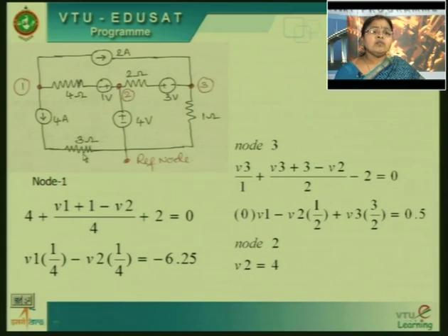So, this 3 ohms, even though it is there in the circuit, will not reflect in any of the equations because the same 4 amperes is flowing through it. One more thing we can say, this is a trivial element. We know the current flowing through it, so you can tell the voltage across it if you want, and it does not have much significance because the same 4 amperes has to flow through this 3 ohm resistor. Okay. So, we have 3 equations, we can solve all 3.